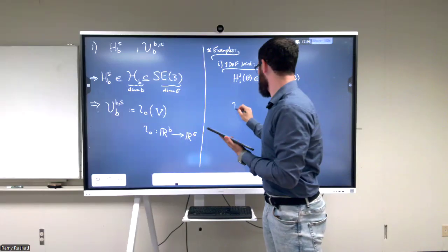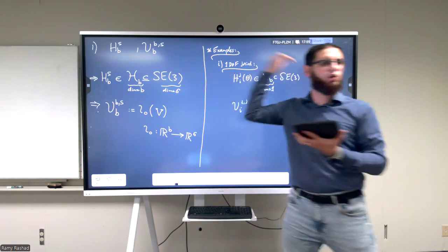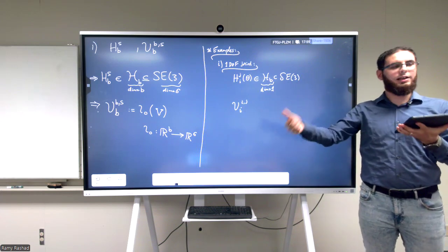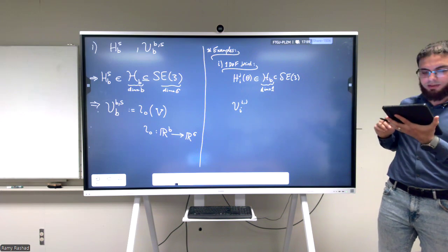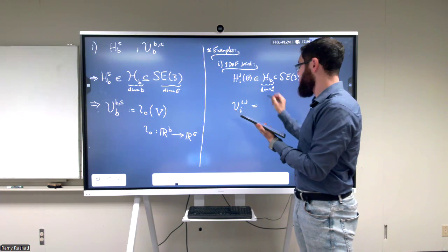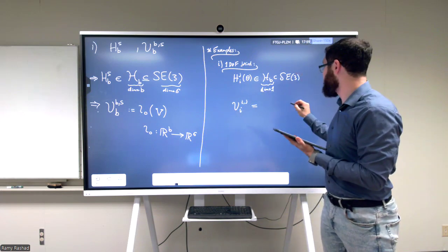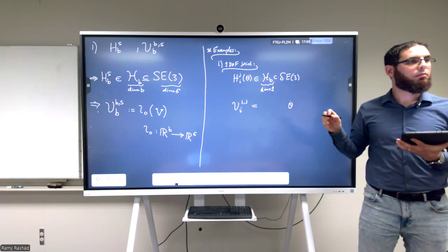What about the V of I with respect to J expressed in I? And here J is I minus 1, right? So assuming that we're connecting frame I, so frame I is one link, frame J is the parent, for simplicity. So this was equal to some map that's multiplied by theta dot, you remember? What was this map?